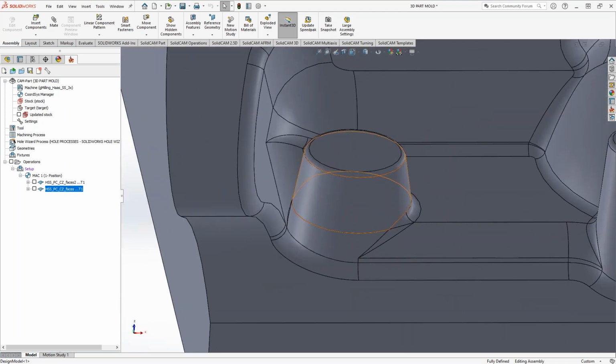Actually, I used this yesterday when I was doing a 4th axis part for a customer, where to do the outside edge of a part on the rotary, since it's one continuous surface, the OD of a part, there really are no edges for you to select in terms of where you'd like to do your wrapped pocketing geometry. Again, something we've covered previously. To get those edges, I use split line. So as soon as I split that surface, now I have edges I can use for my wrapped pocket geometry.